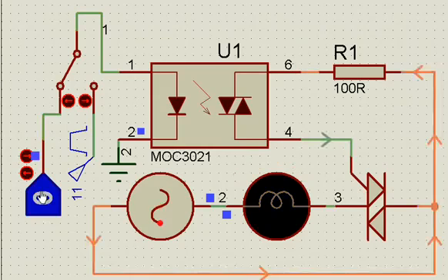And if I make it 0, the lamp stops. Even if the supply is available, the main current is not flowing. It's just because the gate current is also not flowing, though it is showing like this.